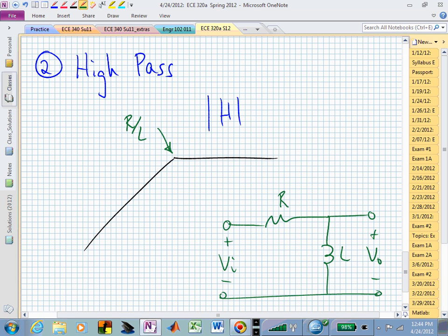It becomes just air, and now you have V sub I and V sub O, and if there's no current flowing through this resistor, they're exactly equal. It's the same voltage. So that's another way of thinking about it in terms of the circuit behavior.